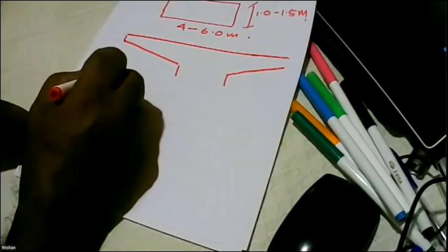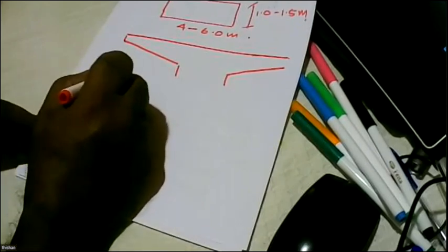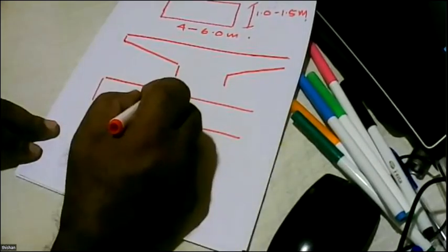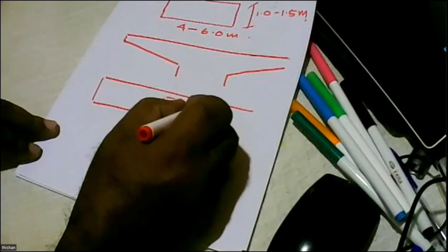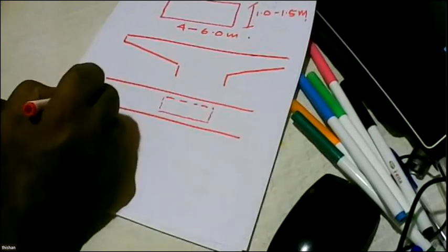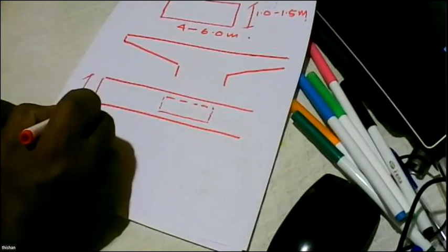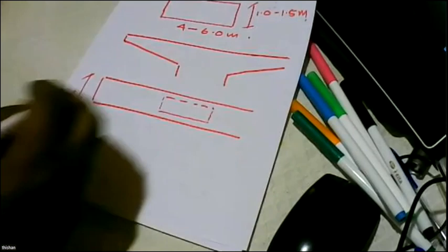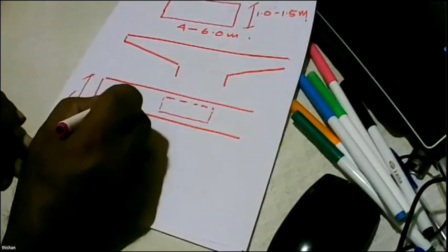So one possibility is to consider, now if you look at the pier capping beam from above, and this is the pier, and the pier capping beam can be wider than the pier. So it's maybe about 2 meters in width, because you need enough space for keeping the beams. So the beams might come like this.